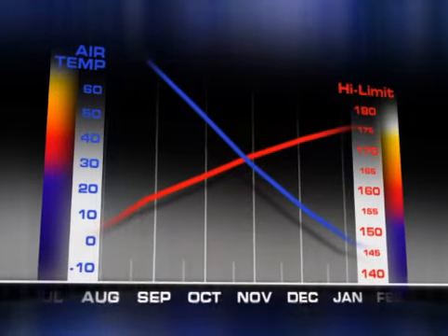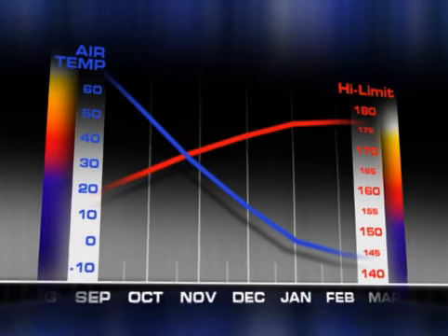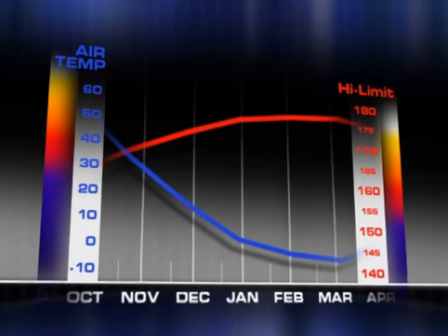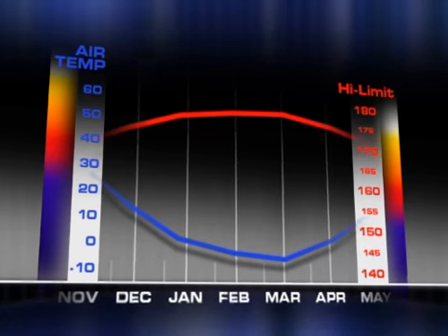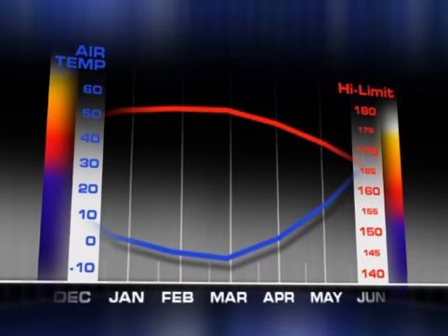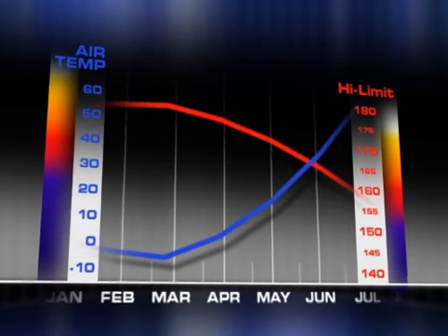Most people wouldn't leave the lights on in their homes for 94% of the time that they aren't needed, but it really isn't practical to expect customers to be willing or able to continually adjust their aquastats as outdoor temperatures change. But there is a way you can help customers with hot water systems to reduce both their energy consumption and their oil bills. Outdoor reset controls automatically adjust boiler water temperatures based on the outdoor air temperature, allowing the boiler to run at lower temperatures during most days of the year.